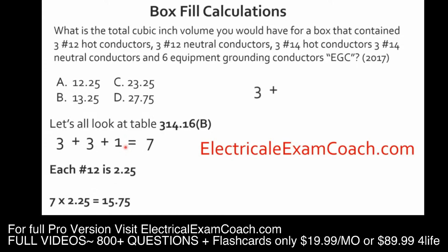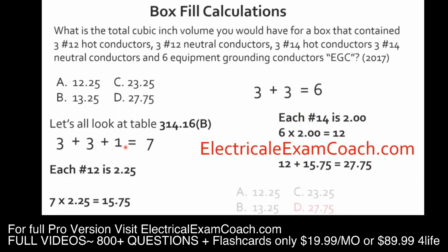Now let's deal with the 14s. We had 3 hots, 3 neutrals, and we don't have to deal with any grounds, they've already been dealt with. We bear that math out, total the two together, and we end up with 27.75 cubic inches.